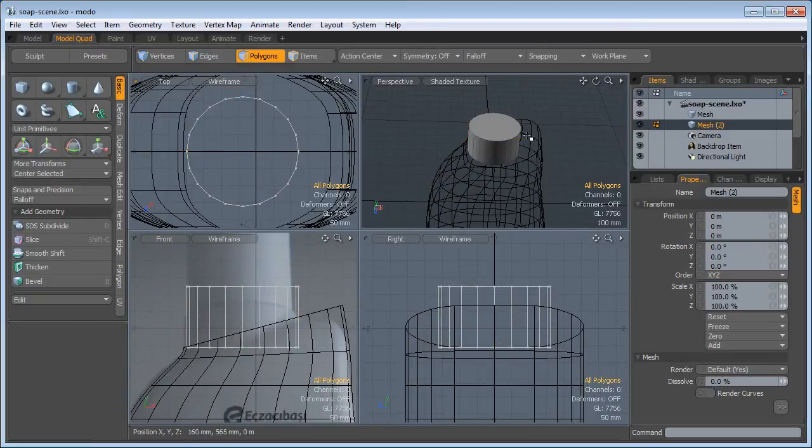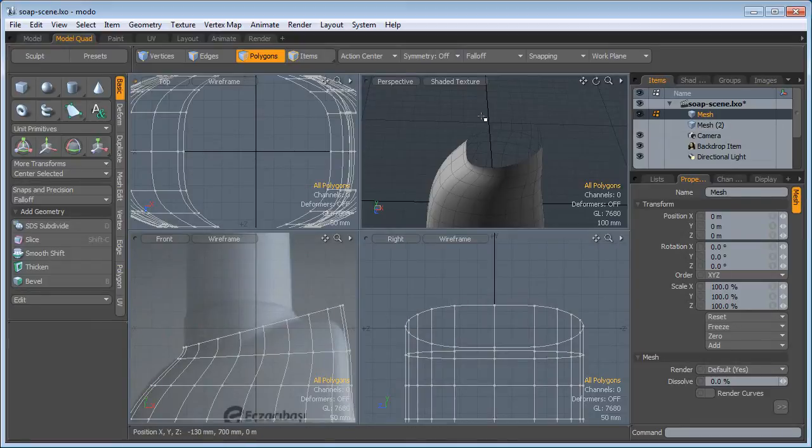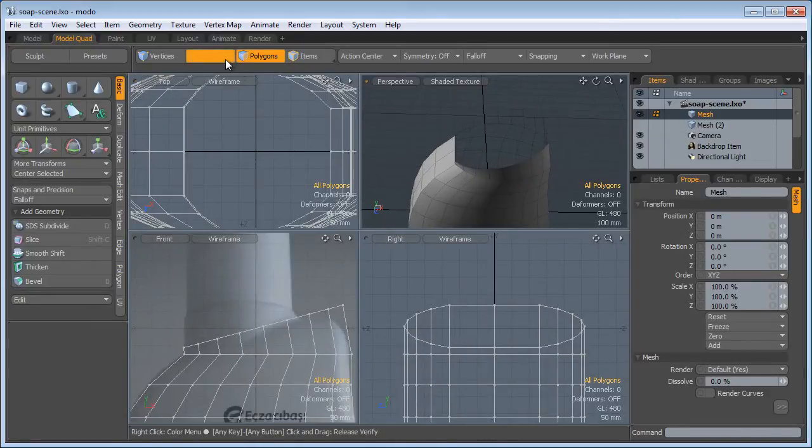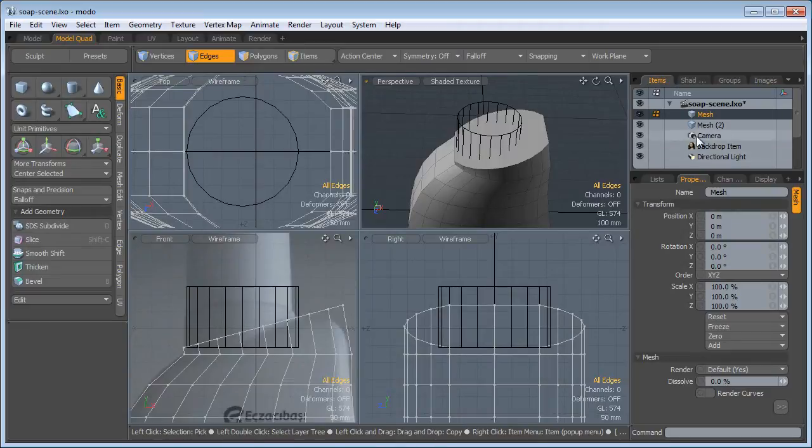Alright, drop the tool. And let's not forget that I need, I'm gonna press tab, I need to select these top edges here, and I'm gonna press P for polygon, because what I'm gonna do is I'm going to perform a Boolean operation, and that will cut through here and will create these 20 points that I'm going to connect the vertices together so I can have quads. So let me show you what I mean. I'm going to activate this.